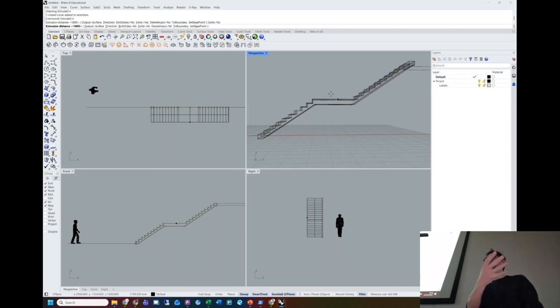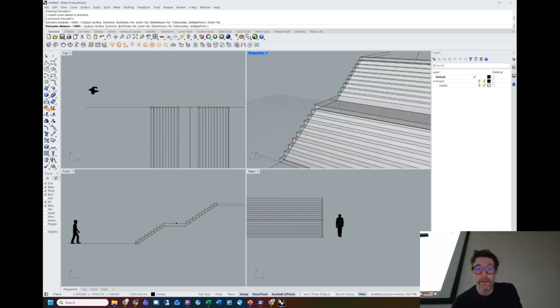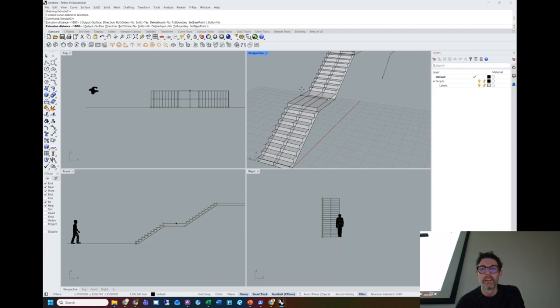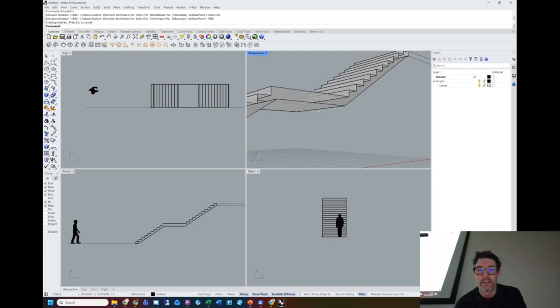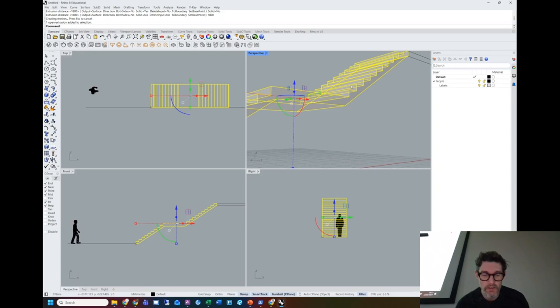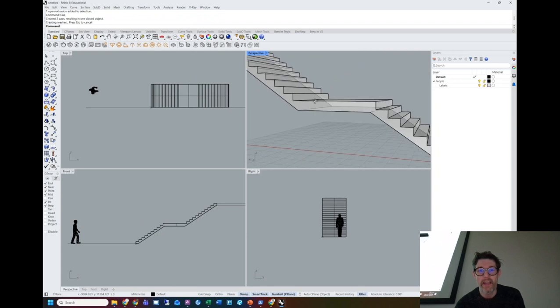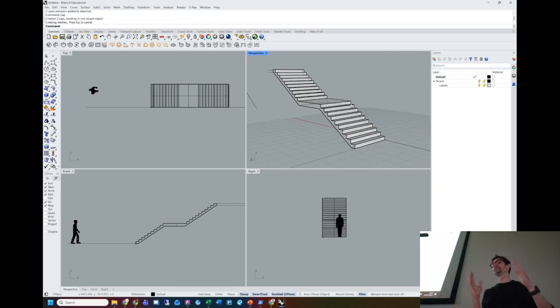Now, sometimes you might want that. So you're using the ability to turn that solid option on or off. And even if you messed up, let's say, oh, man, I've done my 1800, and then you come back later and you realize that you didn't close off those edges. Well, what you can do is tap it and type cap. And then it will cap over any straight, flat edges that it can find in your geometry. So choosing solid is kind of the same as starting with just the surface and capping it. But it's just one less thing to worry about typing in.